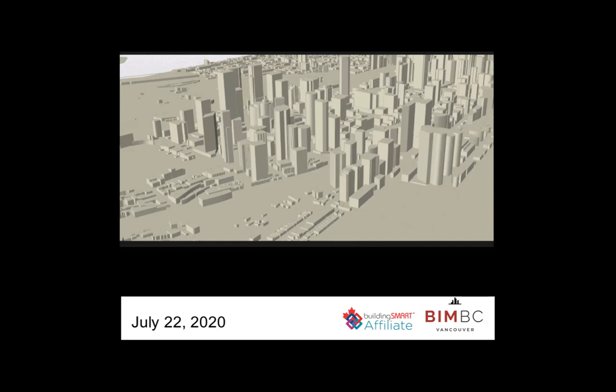These are 3D buildings, just a very rudimentary form, taken from OpenStreetMaps. OpenStreetMaps, another really excellent initiative, lets you draw building footprints. So why not? Every time you do a site plan or initial site survey, why not contribute those back to this open source initiative? All that time wasted tracing roads and buildings at early feasibility stage is just not necessary.